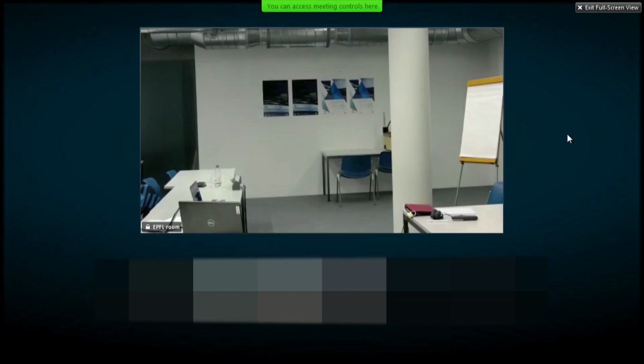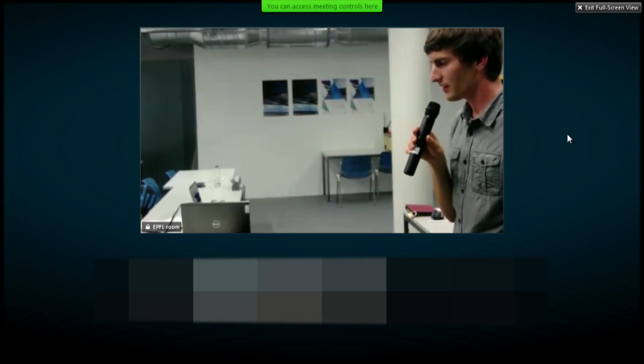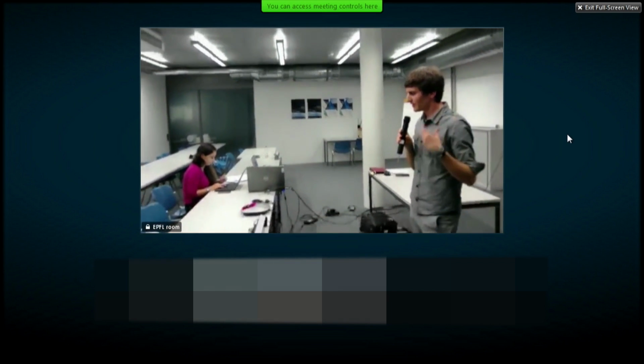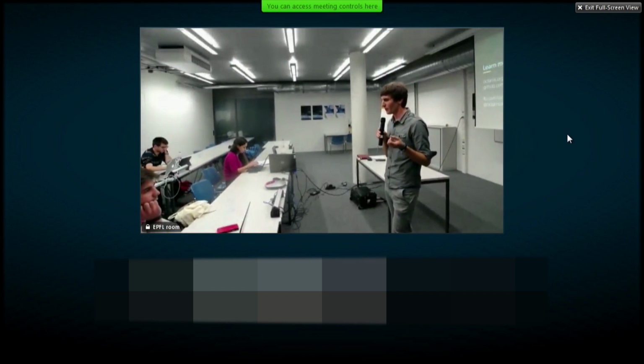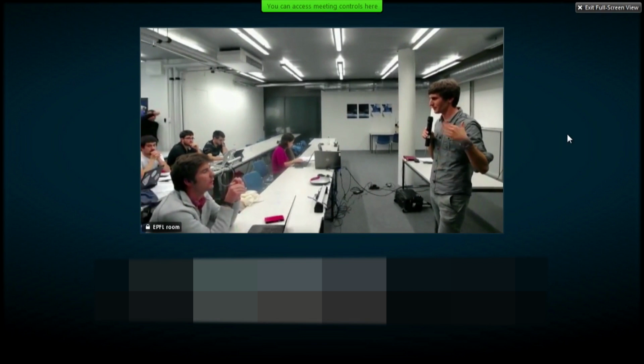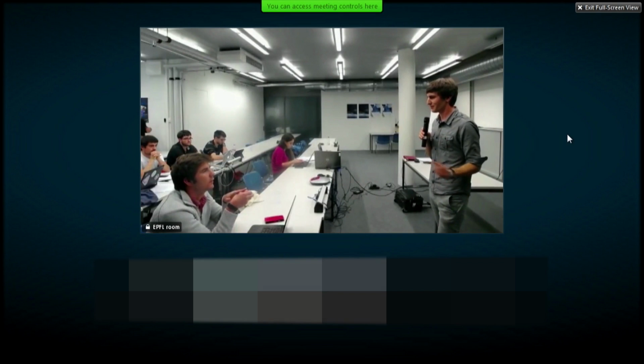Just maybe a technical question. Why did you choose to switch from your first communication to LoRa after? What thing we had before? Yes, and why did you change? Before we had a kind of DIY component that was called HX1. There you basically had to modulate the signal that you're going to transmit yourself. And it was just way too complex. With the new component, you can just send commands by UART, and it will just do its job, and it has higher range as well, and lower power consumption.